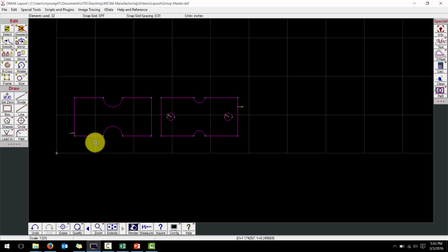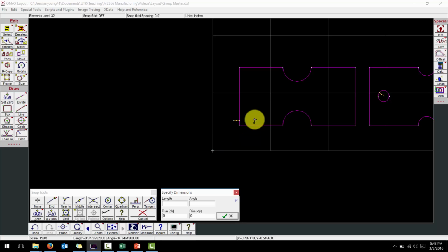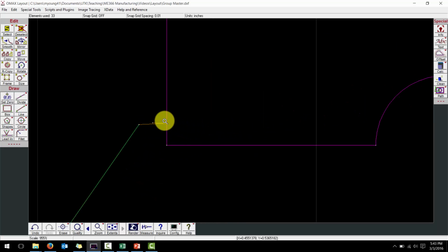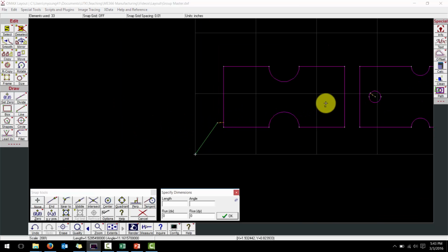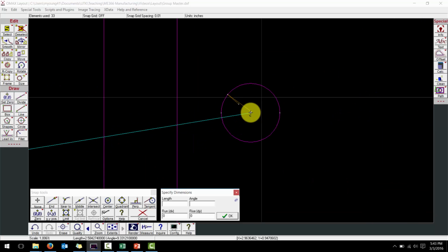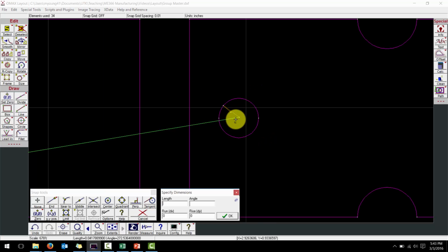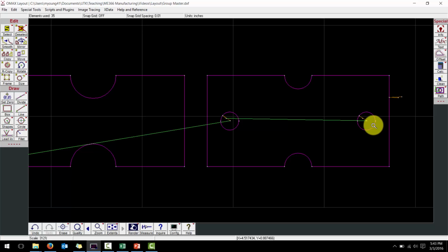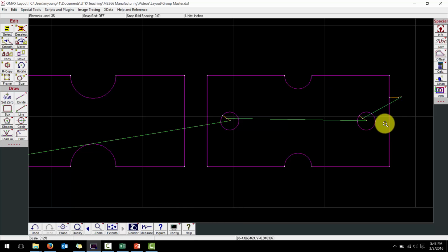I'm going to start the line command. I can do that by pressing L, and I want to start at the 0, 0 point, and then we'll go to the in location. So I'll click here, and we'll do another line command, L. That's where it's going to finish, and over to this location, and L again. We'll continue connecting everything. There's our out in to this one, and then out from this hole and into the final part.